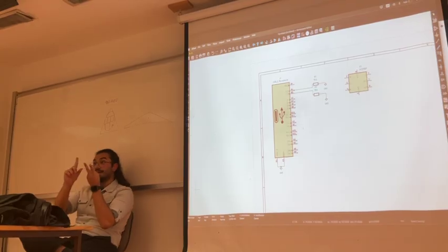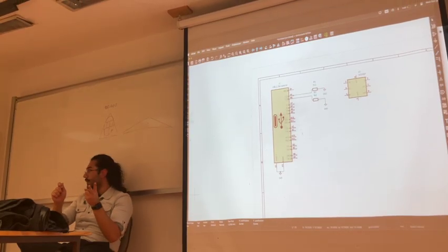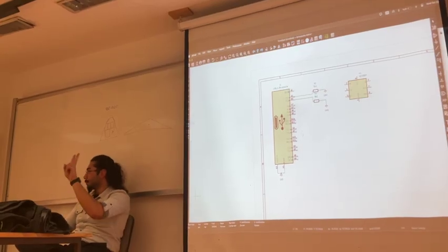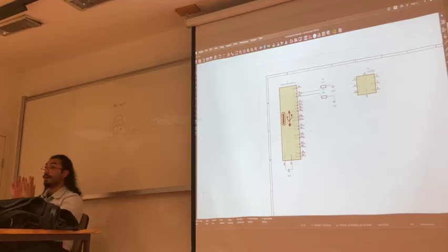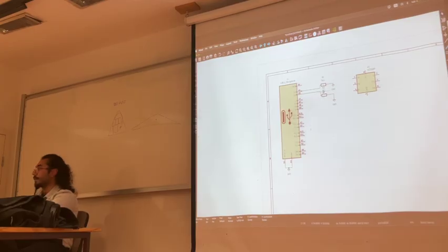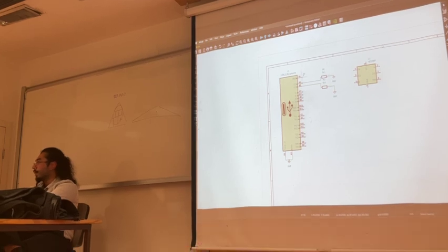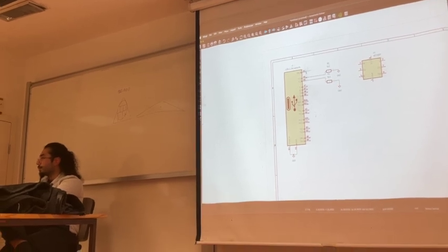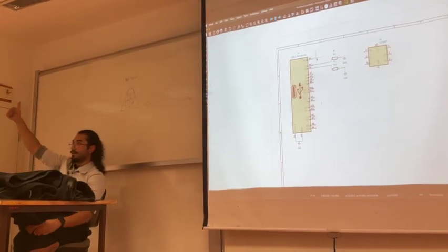Okay, they are important for the people that are going to solder your components on the PCB. Yeah, these two. So we use conventional designs and we try to annotate our schematics as much as we can. So that's why we put 5K1, like we put the values for the people that are going to solder on the PCB. And we are going to do VBus right now. Okay, I am going to use, has everybody got what I'm saying until now?